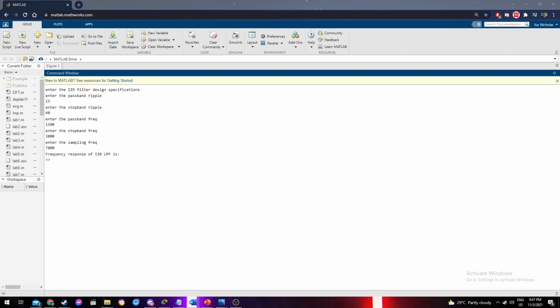In this experiment, we are going to implement a low pass IIR filter and a high pass IIR filter. IIR filters are digital filters with infinite impulse response. Unlike FIR filters, which was the past experiment, they have feedback and are known as recursive digital filters. For this reason, IIR filters have much better frequency response than FIR filters of the same order.